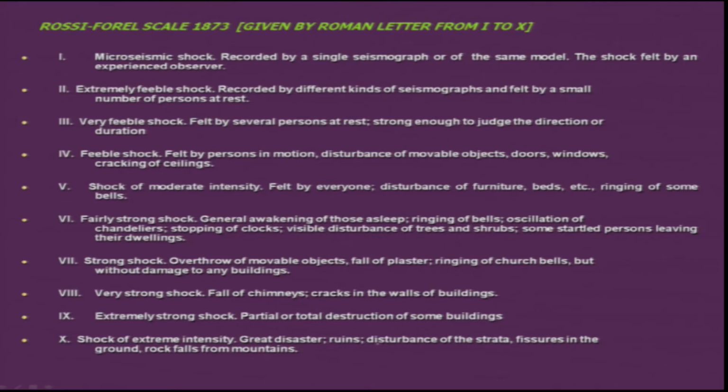Great disaster, ruins. Most of the total damage will take place, and there will be fissures in the ground. The land will develop cracks, and in hilly areas there will be massive rock falls and all that. So this is how the intensity has been described. Locally, seismologists visit to collect the ground truth, and then they assign which area had what particular intensity during the time of an earthquake.